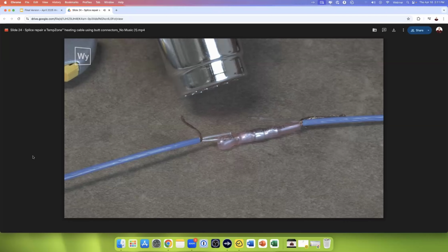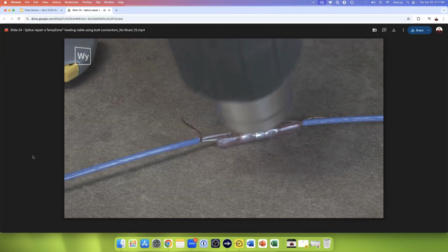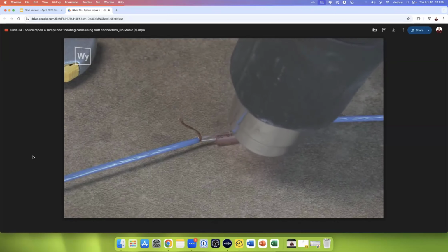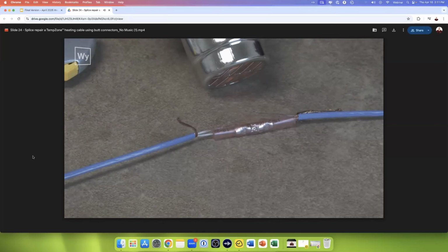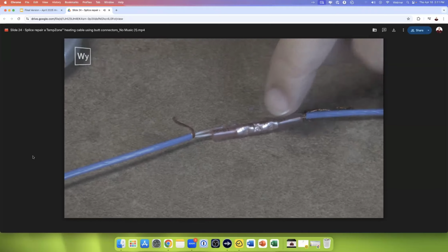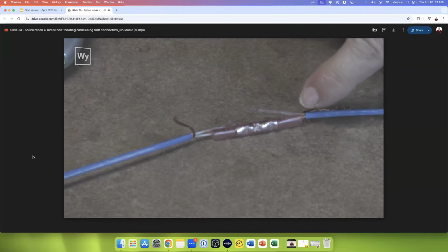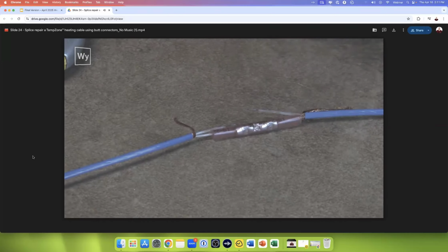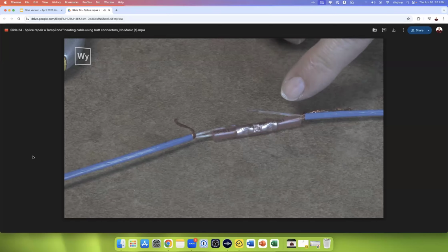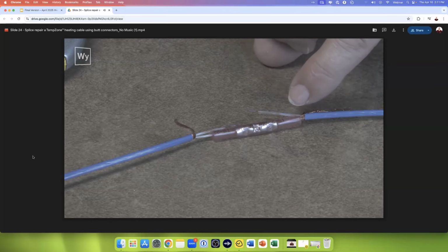You can also do this with solder, but you have to have a good talent with a soldering iron to do that. That's why we're showing this side. A quick look here, you can see where our solder has melted in the center, and we can see our wire very well through the pink connector. If you can see it really well, that means it's gluing itself onto the wire. So we can get a good idea whether our connection is going to be good. So we have a nice clear wire that we can see.